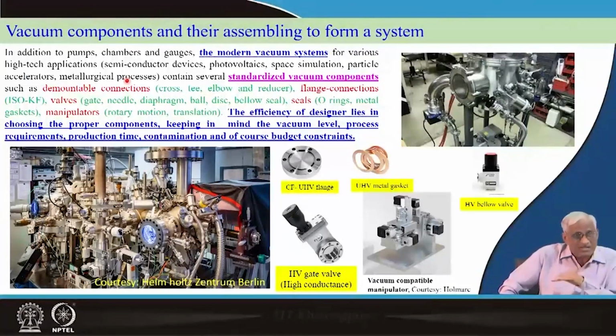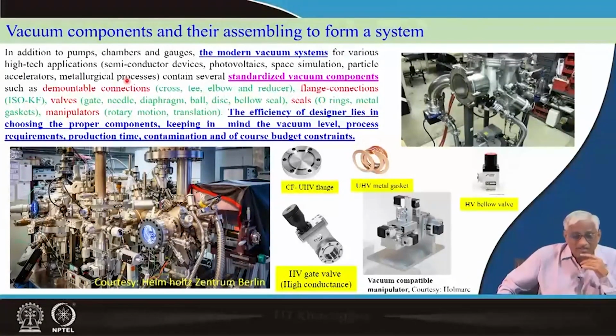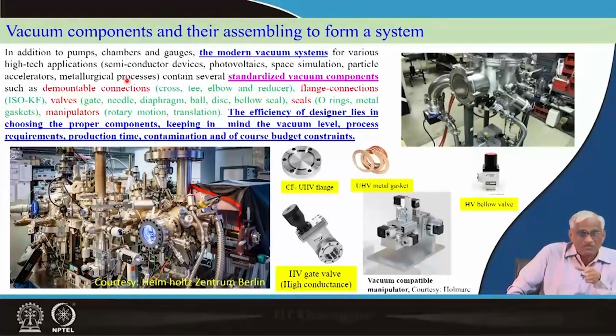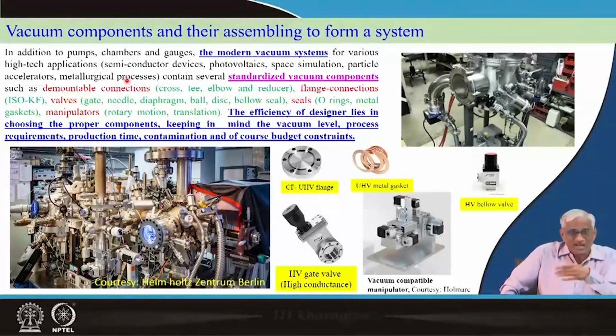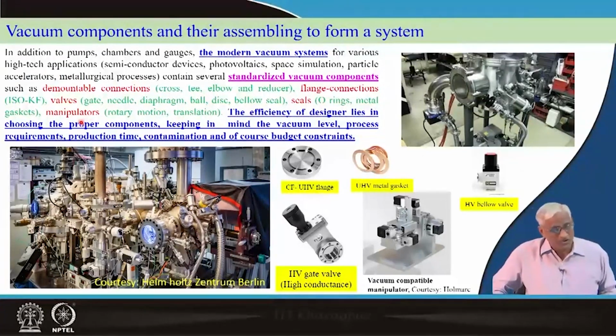There are metallurgies in different levels. Later we will see, for example, steel degassing at 10^-2 torr type, 10^-3 torr, whereas a very specialized alloy ceramic to metal joining, that is done at 10^-7 torr for interrupters. That is also vacuum metallurgy, this is also vacuum metallurgy, but levels are different. We will see all that later. Anyway, we are going to take a vacuum metallurgical furnace in the next class for making a system design approach from various aspects as a trial run. So, that is taken as a tutorial for you.